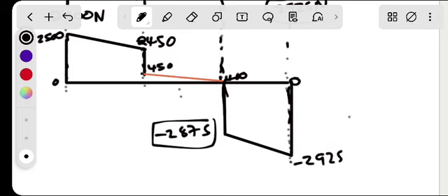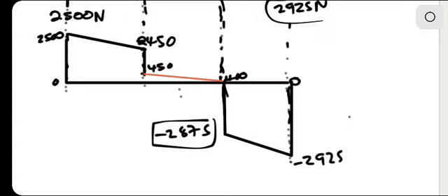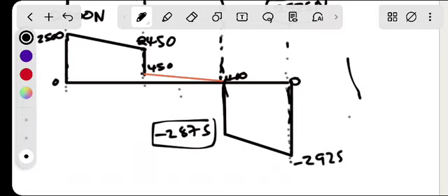So why are we calculating this? Why do we draw this? Because the maximum bending moment is acting at the position where the shear force diagram cuts at 0. It cuts here at 0. That is where we'll have our maximum. So our maximum will take place there, where it cuts at 0. And this distance, guys, we know all those distances.